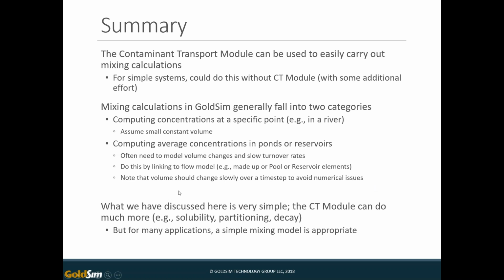Again, I also want to point out that what we've discussed here is very simple. All we've done is mixing, right? The CT module can do way more. It can deal with solubility, partitioning, decay, movement of particulate matter, lots of bells and whistles. Treatment, you can model a treatment process, lots of bells and whistles. However, for many applications, a simple mixing model is where you should start.